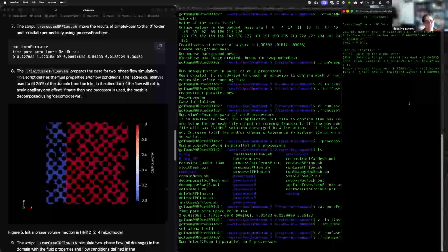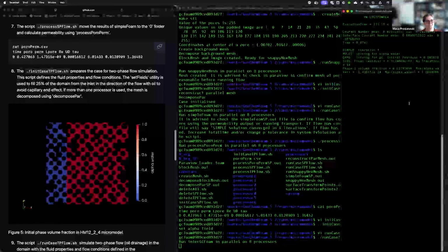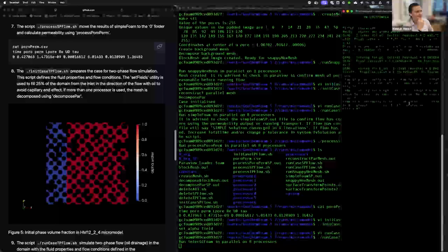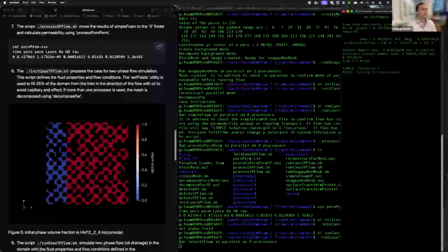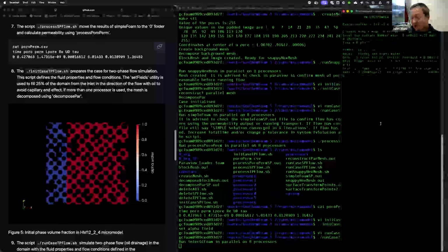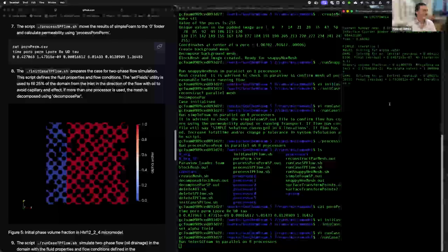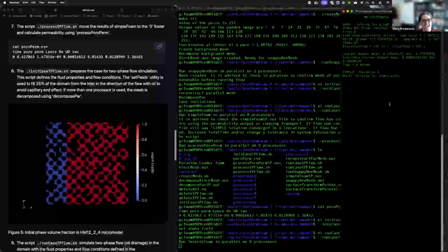I guess what that roughly means is your numerical method shouldn't run faster than the process itself because it's going to get unphysical. How's that? Yeah. Okay. Multi-phase flow is much more complicated. If it was just the Courant number, we'd be happy. Agreed. There's also the capillary number, right? So there's so much.